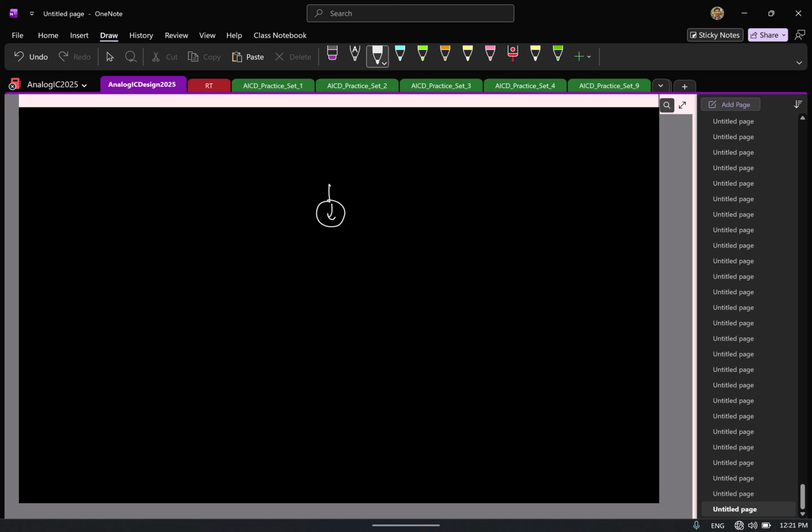I can't put a current source and then say that, hey, my gate voltage will be set automatically. That is like saying switching on the switch and the fan turning on. There should be some kind of feedback, because here again you have the same thing: one current source and another current source. So there should be some feedback to set this voltage, and that's what we are doing here. An extension is this common mode feedback. No big difference.